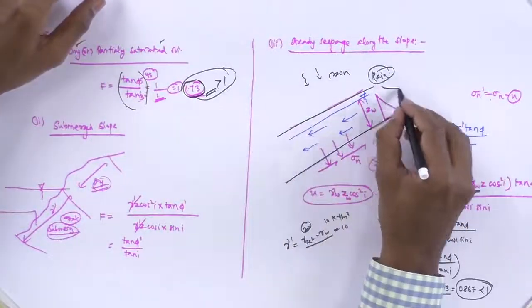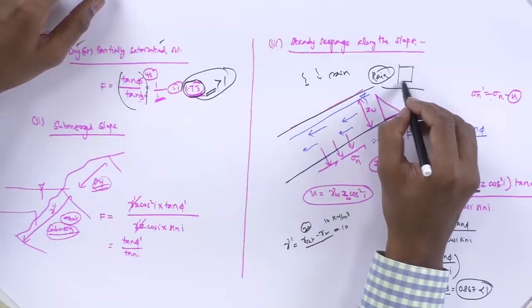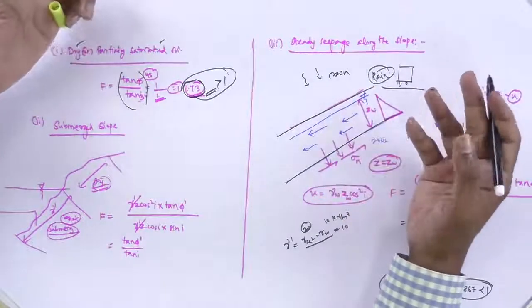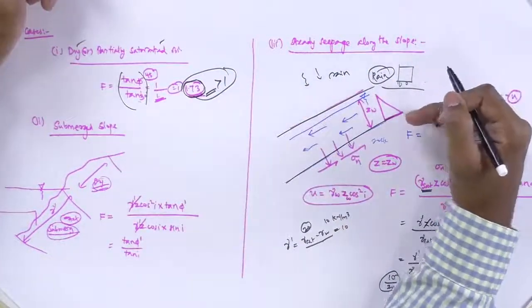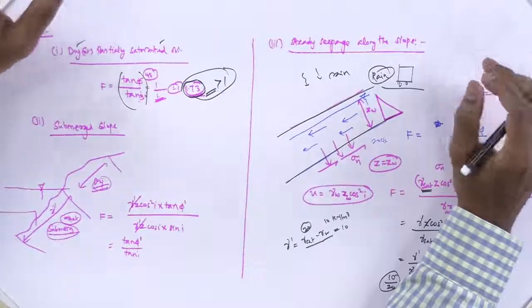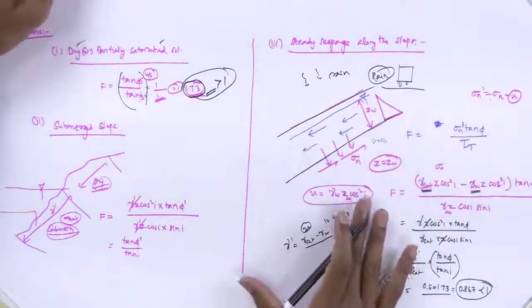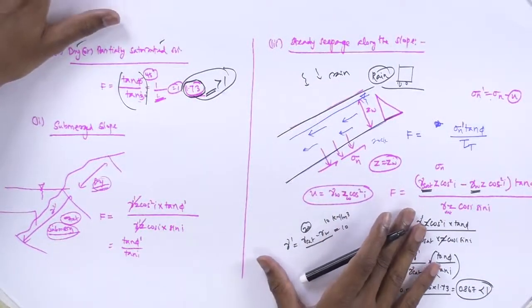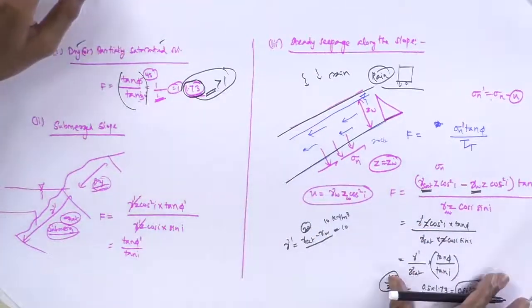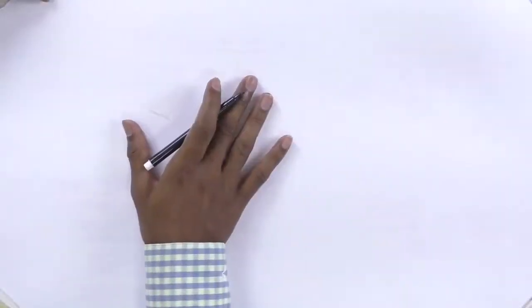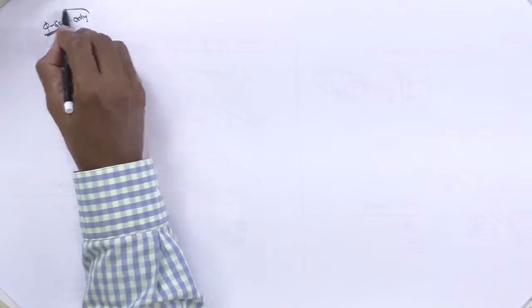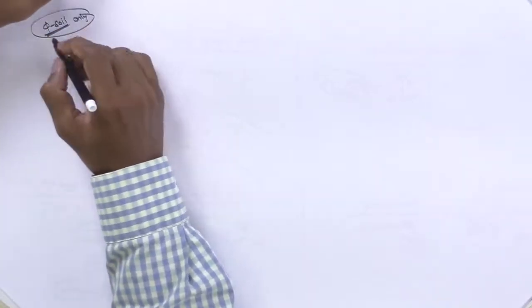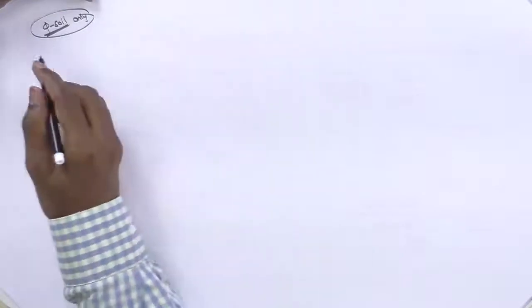There are some other several cases, so this earth slope may take any vehicle load, and there it may change. For the different cases like this, I have explained 3 cases here, so likewise case 4 and case 5 can be explained. We have to test the factor of safety for all the cases, and the worst case factor of safety needs to be taken into account. What we have seen up to here is the factor of safety analysis on phi soil only, slope stability analysis.